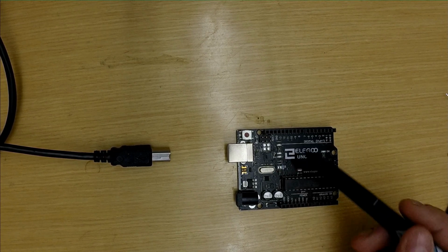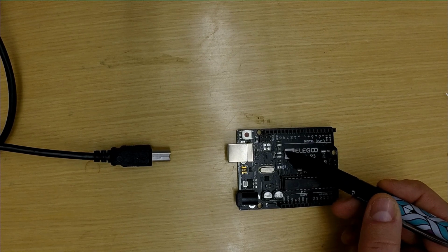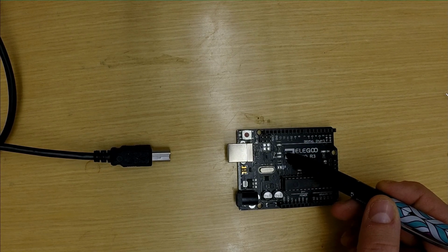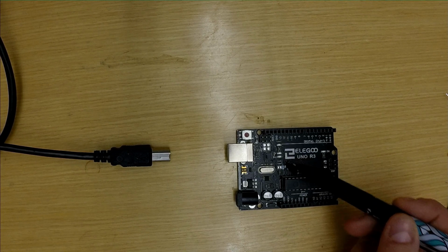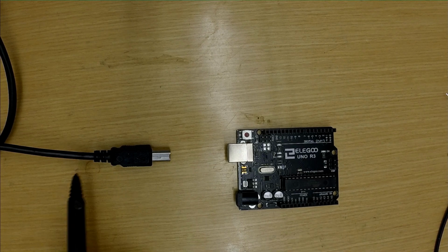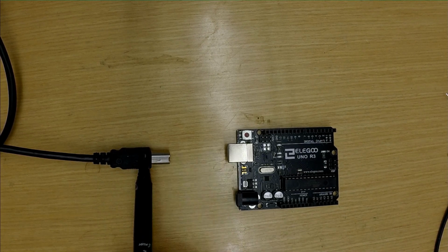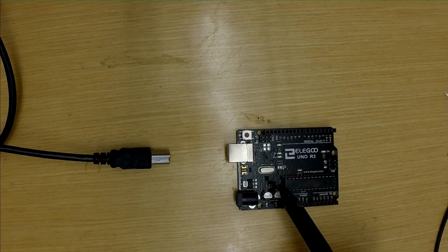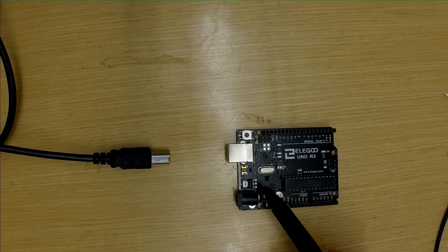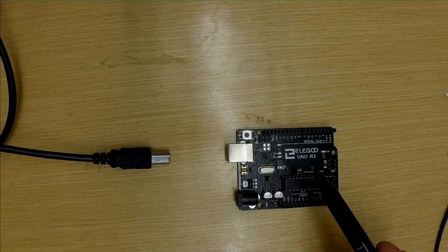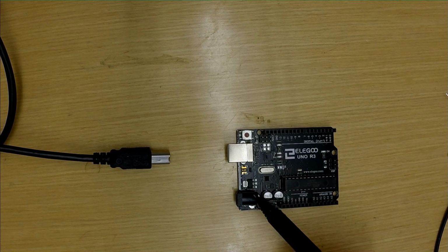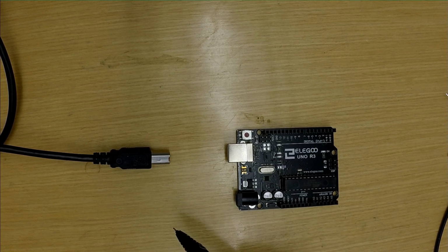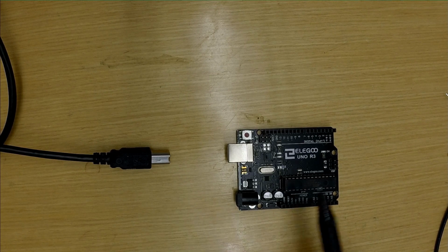Other things that you'll want to pay attention to is right below this pin 13 LED, there's two other LEDs. This one's labeled TX and the one below it is labeled RX. Those are the transmission and receiving LEDs. So those indicate if we have activity coming in through our USB port. If information's being exchanged through there, you're going to see those LEDs light up. So we'll watch when we decide to upload our first code to the Arduino. You're going to see these LEDs blinking back and forth as the Arduino is reading in data from the computer and getting that loaded into its memory so that it can start actually executing code.